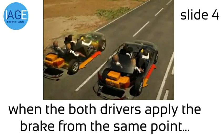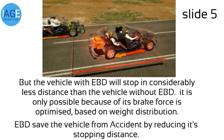when both drivers apply the brake from the same point, the vehicle with EBD will stop in considerably less distance than the vehicle without EBD. This is only possible because its brake force is optimized based on weight distribution. EBD saved the vehicle from an accident by reducing its stopping distance.